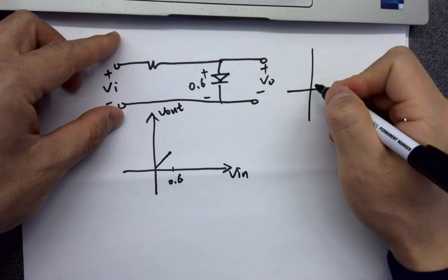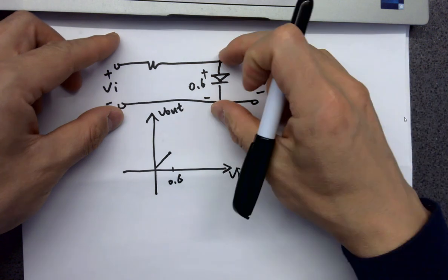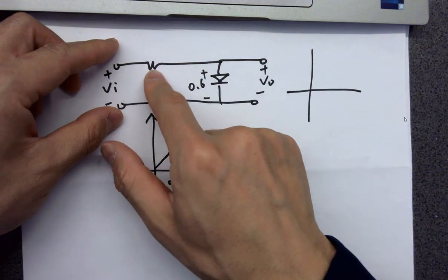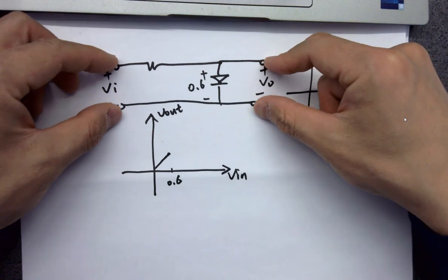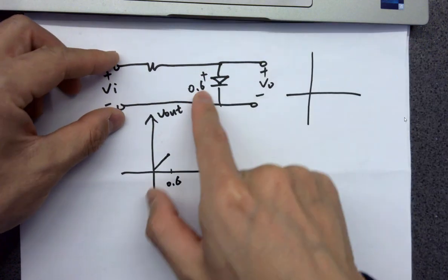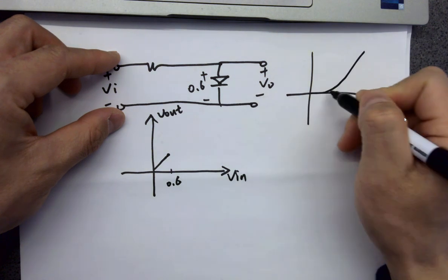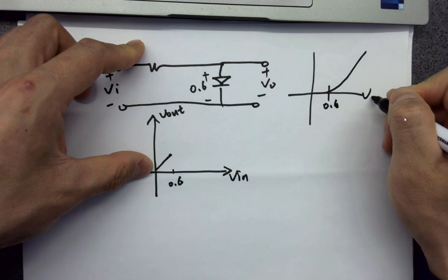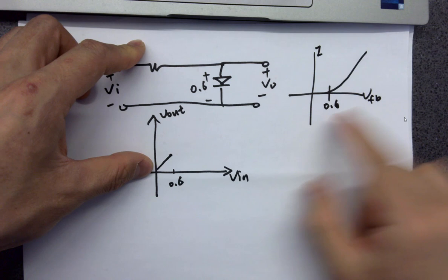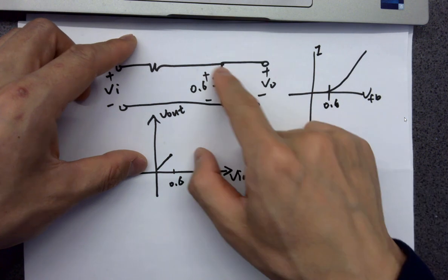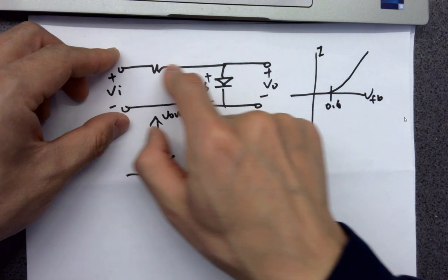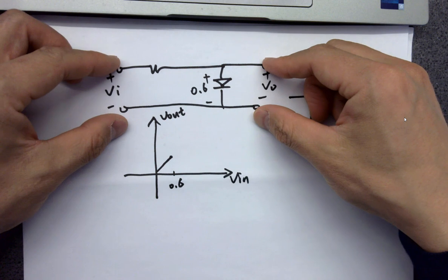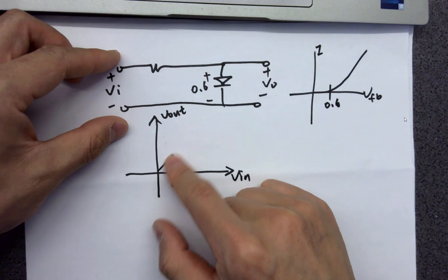There's a voltage drop, but the thing is, no current, so it's okay. You don't have anything connected to the nodes, do you? No, nothing. Before it reaches 0.6 volts forward bias, there's no current in the diode, and no current means no voltage drop. That means V in equals V out. Does that make sense? That's why it's a linear curve.